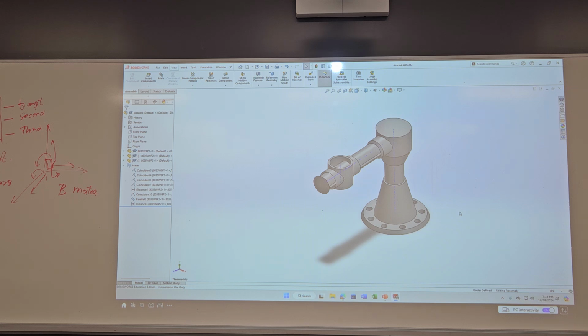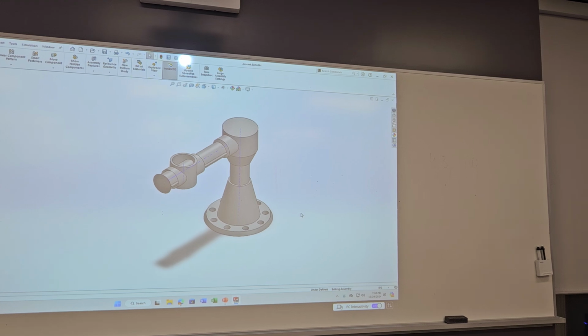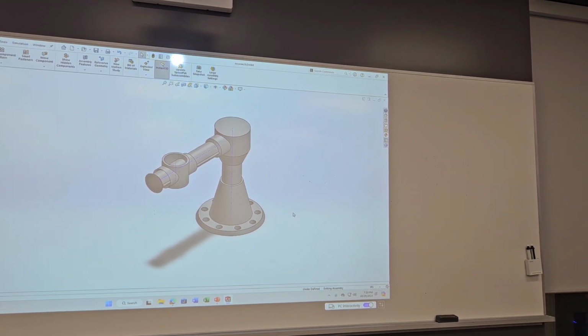Select the faces. This face. This face. And then say this face. And numbers. No, not 0. Zero, you don't need 0. You can coincident. You can, but we already did. That was the first time, but it's still going to rotate. So to stop that rotation, you need another, which is your design intent of those wedges. You can make the plane so that it won't rotate.